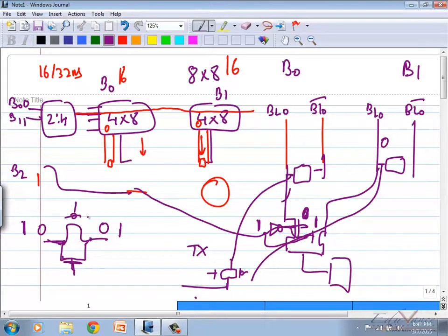There is no read enable. That is sense enable. Data bar. If you want to write a 1, you understand that structure. Accordingly, one side will get pulled down. Obviously your rows have to be activated as well. Where will that row be activated from? From the row decoder. So you have to take the decoder delay also into account.